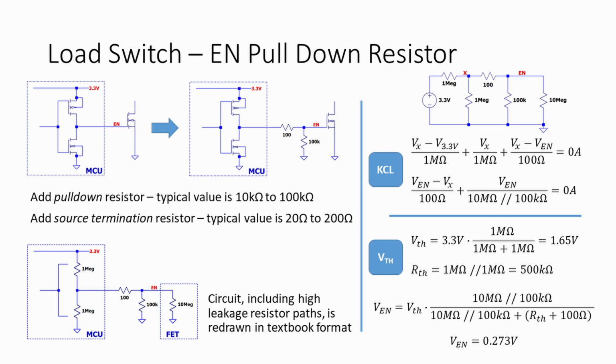You might go outside the 10K to 100K ohm range if it makes sense for your design, but let's say we want to lean on the power-efficient side of the trade-off and choose a 100K resistor. If we use a resistive model for the leakage, we can turn the microcontroller GPIO stage and the MOSFET into a circuit that looks more like what you'd see in intro-level electronics classes.